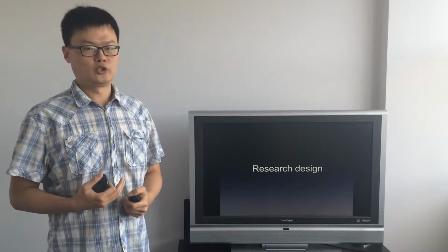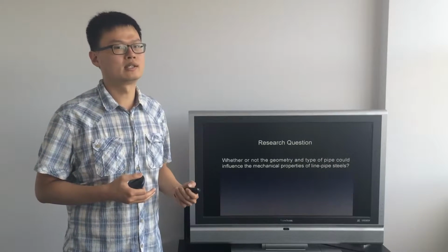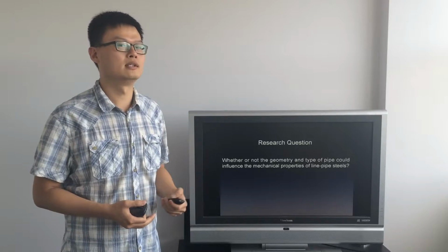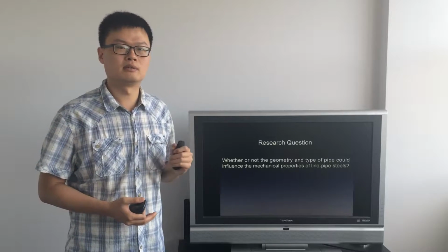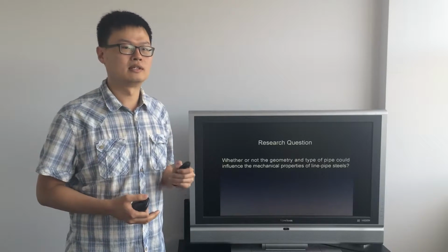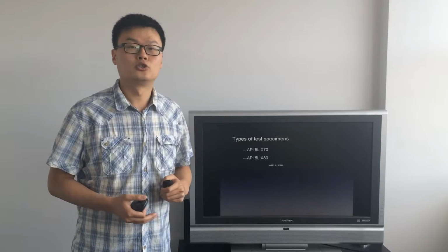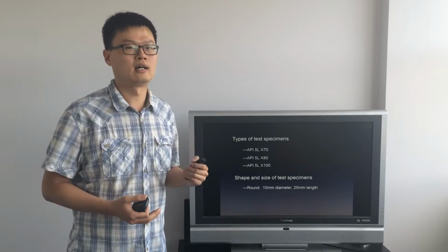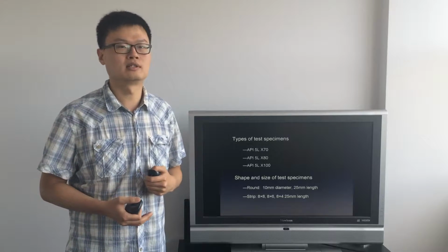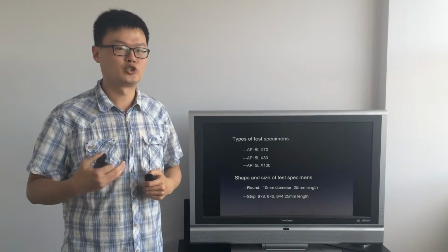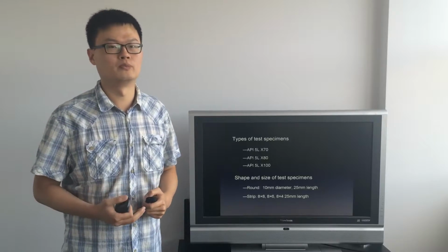After reviewing the previous research, I designed the research for my topic. Firstly, what is the question I will study? The main question is whether or not the geometry and the type of the pipe influence the mechanical properties of the pipeline steels. Therefore, I selected three types of pipeline steels, which are X70, X80, and X100, to investigate the relationship between the type, geometry of specimen and stress-strain behavior, yield strength, ultimate tensile strength, and yield-to-tensile ratio.